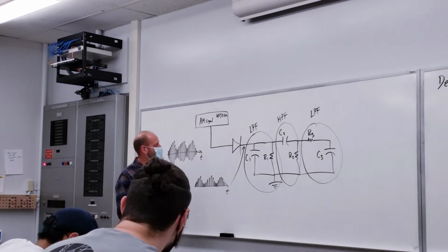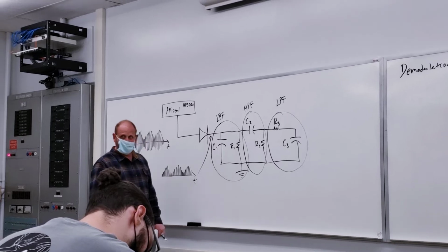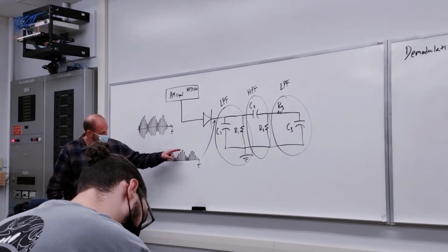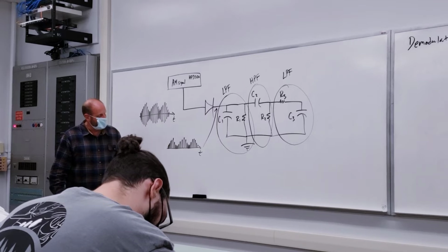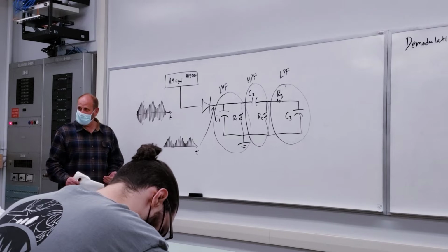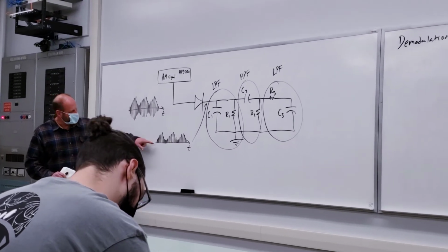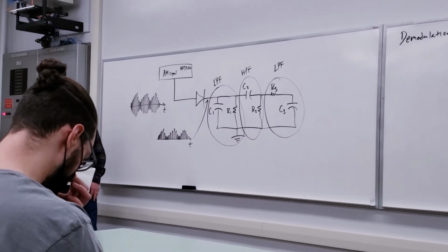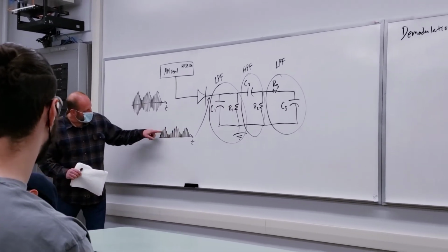All right, next, the low pass filter section. We set it up so that the tau of the circuit is just right to follow the low speed variations of the message, but a circuit that is too slow, with too much electrical inertia, maybe we could call it, the tau. The bigger the tau, the more electrical inertia. It just wouldn't be fast enough to respond to the quick, high frequency carrier variations. So we want to make that tau just right, so it'll follow the message, but not the high frequency stuff.